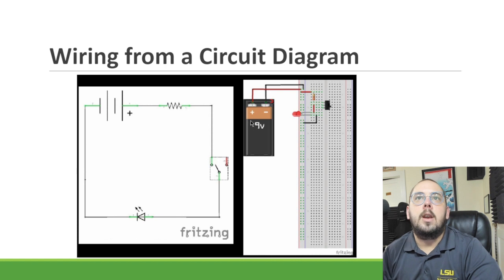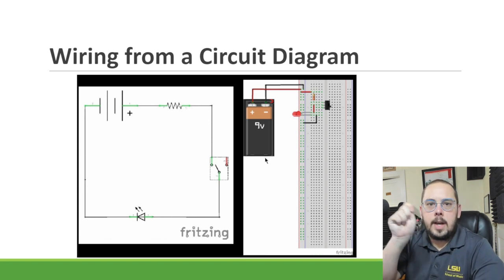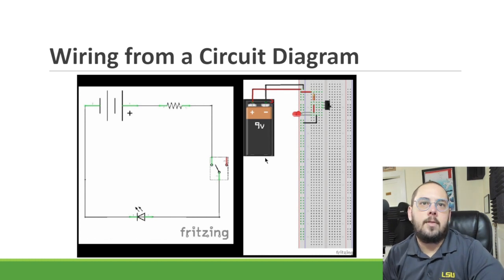We start on a battery. We have the positive end of the battery going into our breadboard to the positive. So that's going from positive to a resistor, to a switch. One end of the switch isn't connected to anything, we see that. The other one is connected to the LED. And then we go from the LED to ground. So this serves as an LED with a switch that turns it on and off.